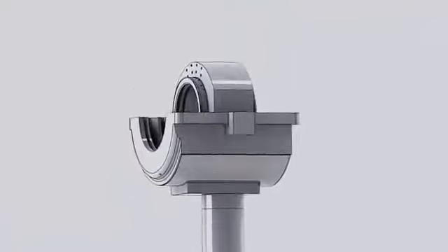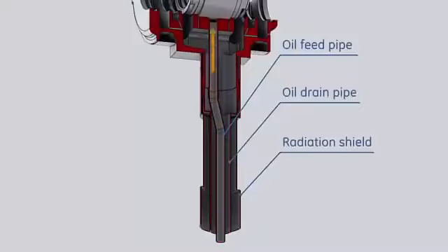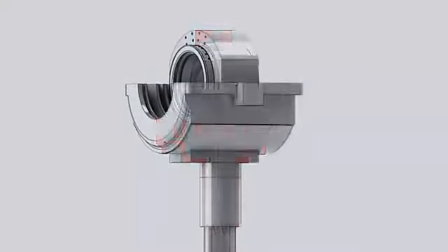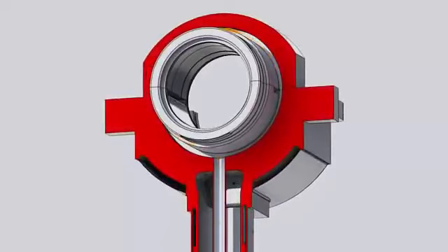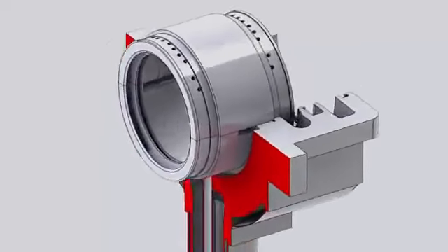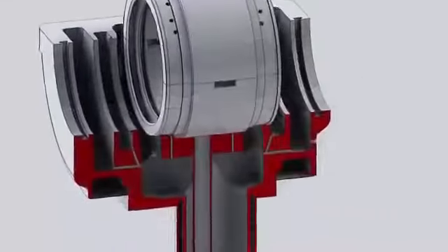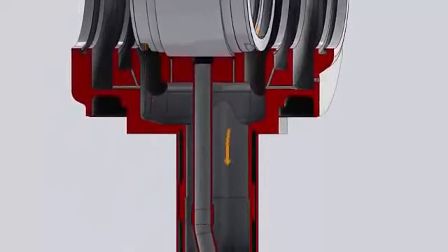For lubrication, oil is supplied through the oil feed pipe to a port in the lower bearing housing, where oil fills the annular space around the liner and is admitted inside the liner through two grooves machined at the horizontal matching edge. Oil deflectors are mounted on both ends of the liner to help containing oil inside the liner. Oil is drained through the vertical drain slots at the bottom of the lower liner half to the lube oil drain cavity, down to the oil drain piping.